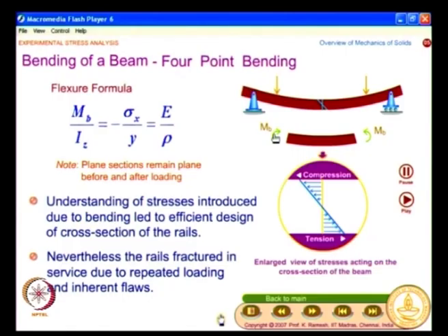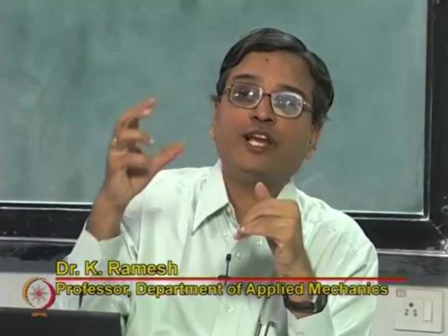So in a first level course, you will learn how an axial member supports load. That is why you have a lot of trusses being used in stadiums and very large halls. So you effectively utilize the role of material completely, because all the material contributes to load sharing. The moment you come to bending, you understand that stress is varying linearly, so the inner core is not contributing to load sharing. And what is seen when you go to how this is used in design?